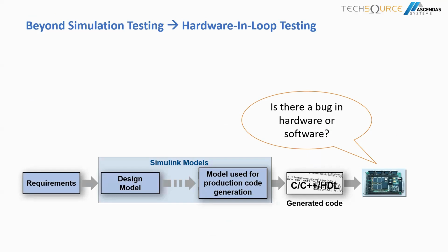In this case, we are directly checking battery testing. But of course, battery testing on the actual physical battery is costly. It may also be slow, and maybe unsafe if, for example, you're testing fault scenarios. So instead, we may use battery emulation, which is developed with hardware-in-the-loop or real-time systems.